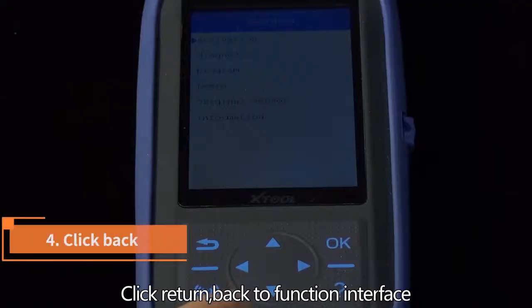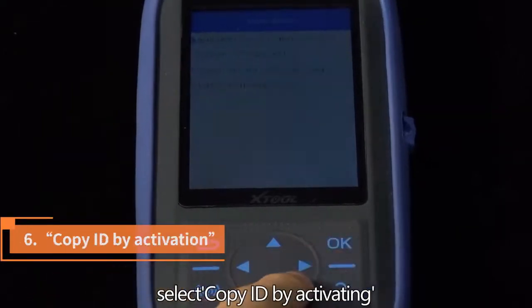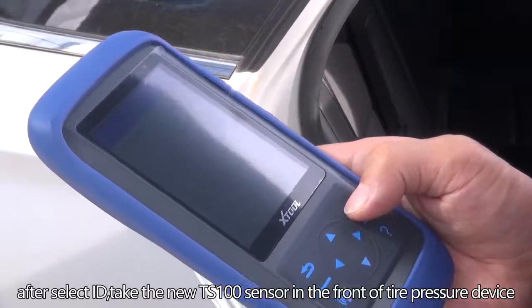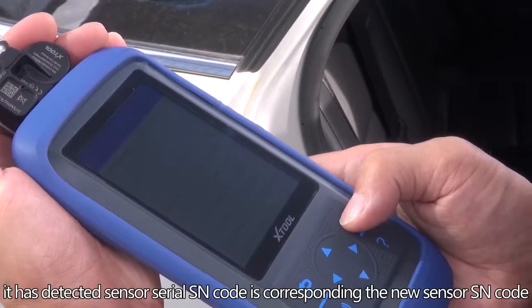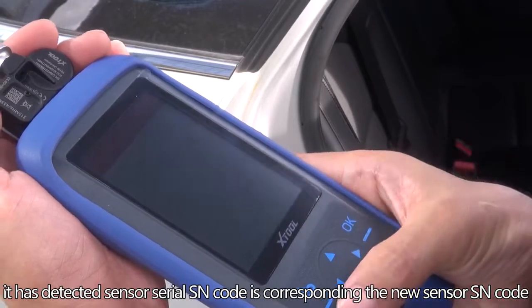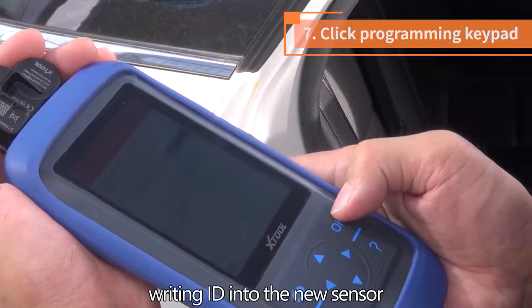Click Return back to function interface. Select Programming. Select Copy ID by activating. After selecting ID, take the new TS100 sensor in front of the tire pressure device, enter programming interface. It has detected sensor serial SN code is corresponding to the new sensor SN code. Click programming keypad to start writing ID into the new sensor.